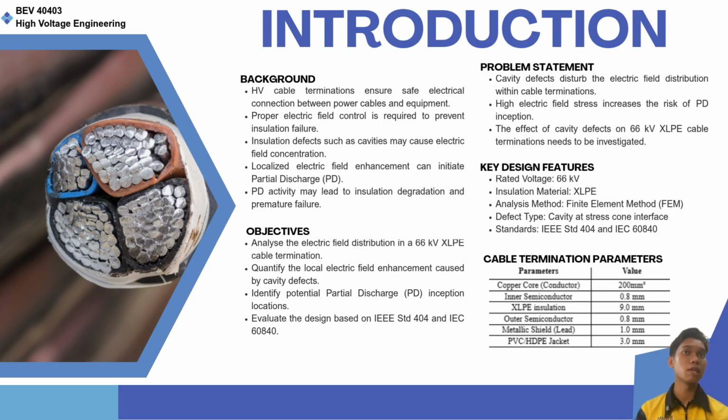Second, we move to the problem statement. Cavity defects disturb the electric field distribution within the cable termination. The resulting field enhancement increases the risk of partial discharge and reduces system reliability. Therefore, the impact of cavity defects on a 66 kV XLPE cable termination must be investigated.